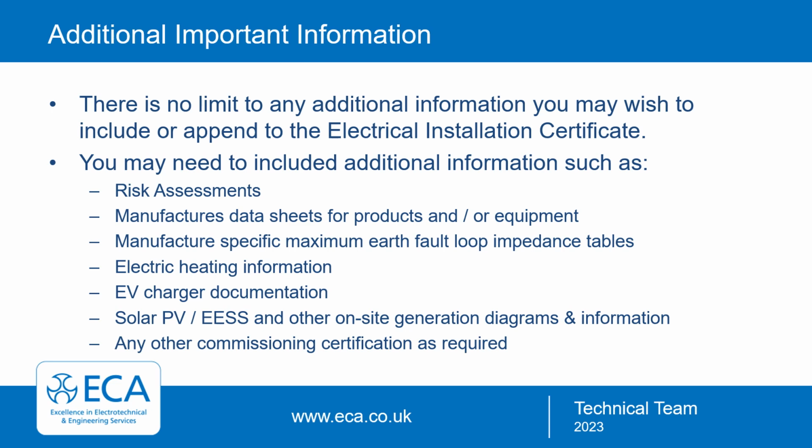You may wish to include items such as risk assessments, and that's particularly needed if you have omitted RCD or SPD protection, manufacturers' data sheets for products and/or equipment, manufacturer-specific data if you're using their maximum earth fault loop impedance tables rather than those in BS 7671, electric heating information, EV charger documentation, renewables and storage such as solar PV and on-site battery systems or other generation systems, diagrams, other information, commissioning certificates. All these can be added if required.